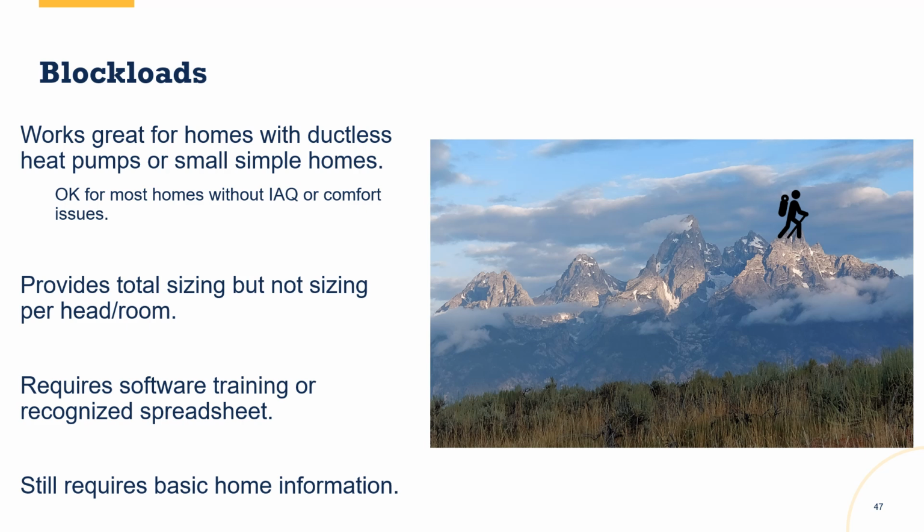Block loads work great with homes that are ductless or simple homes. In most homes without indoor air quality and comfort issues, as long as I've got some decent data collection, block loads are going to work great for most of those homes. It provides total sizing, just not per room or per head. It still requires some software training and or recognized spreadsheet training, and you still need to get a lot of the basic home information. But the good news is you're still pretty high in the mountain range with your results here.